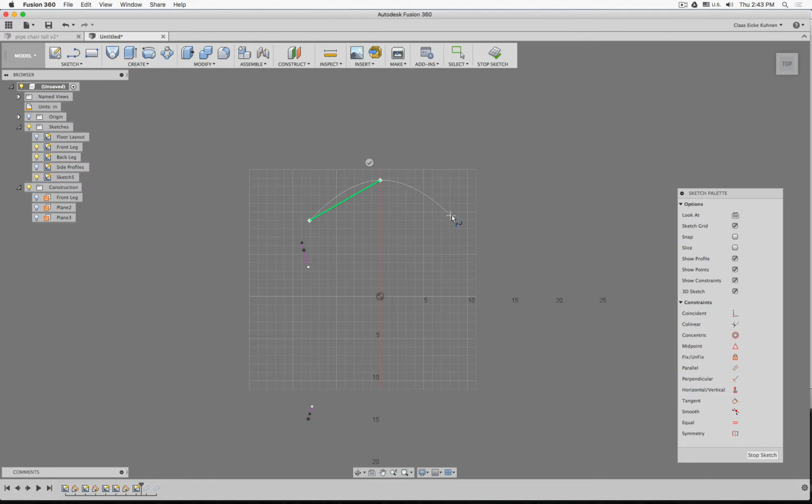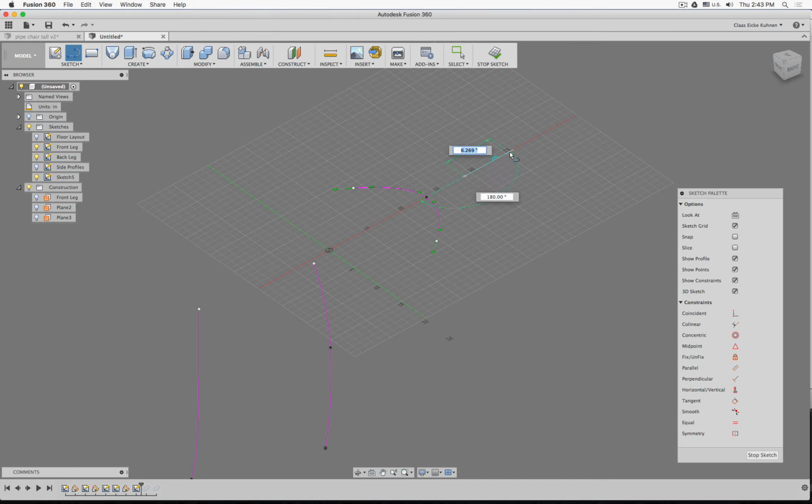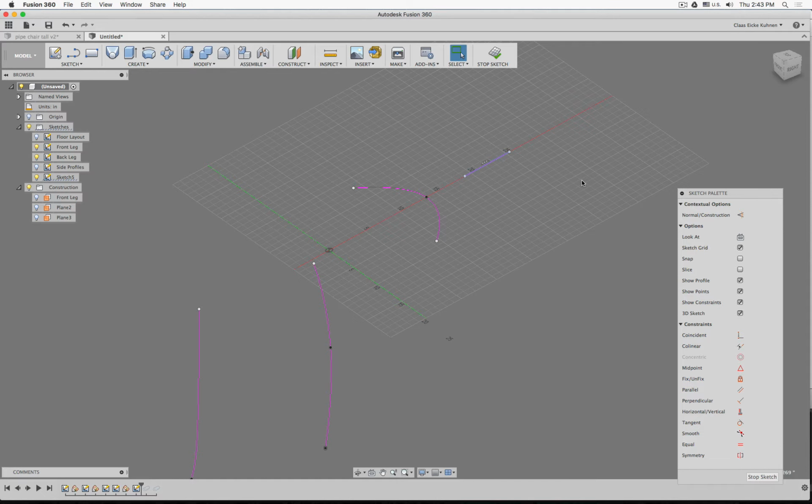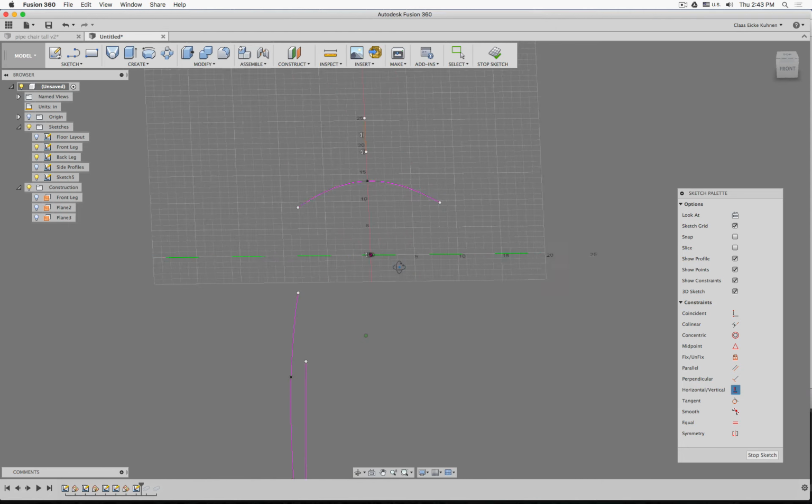So I can work with a sketch, a spline, and just put 3 points down. But now I want to be able to make sure that left and right halves are perfectly symmetrical. I can somewhere, either from the center or somewhere to the outside, I like doing it this way a lot, make a line, switch it to construction, and then I say this line is vertically aligned to the center point.